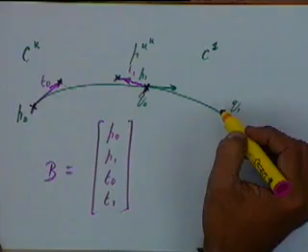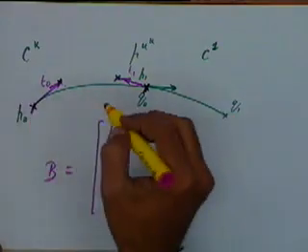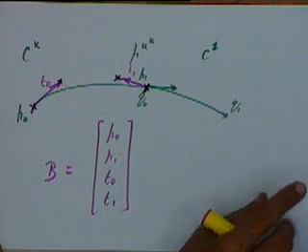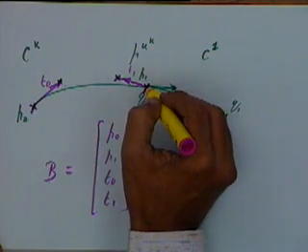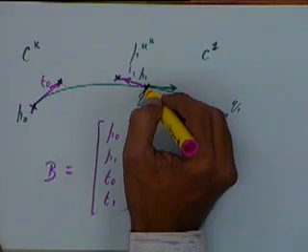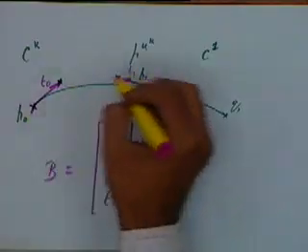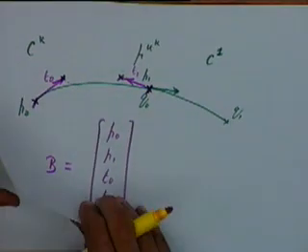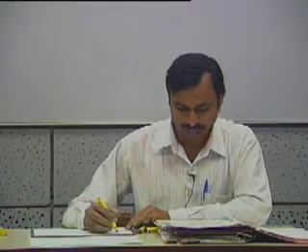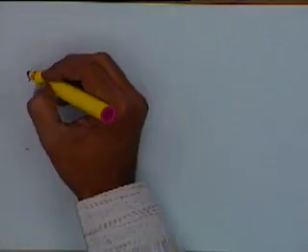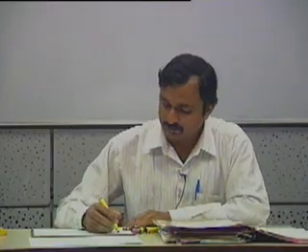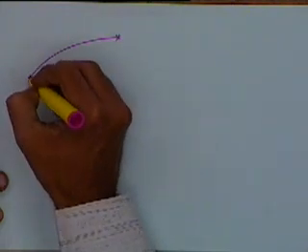But if you are modeling a curve in any application, which consists of a series of such curves, we need to ensure that continuity at the common endpoints is maintained, because we do not want a discontinuous curve in most applications. So, let us take a simple case where we have two curves and we want to ensure that they have a C1 continuity at the common endpoint. Let us say we have one curve like this.